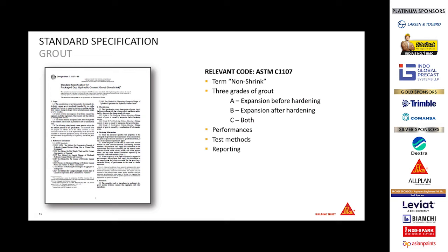Unfortunately, whenever I see the specification, especially in precast or for many of the application areas, I do not see a detailed specification. And from this forum, I would like to request the designers, because you can understand that the designer's design is at stake if the connection fails. And the connection is totally dependent on the type of grout and the performance of grout. So they must give a clear specification for the type of grout and the performance requirement.